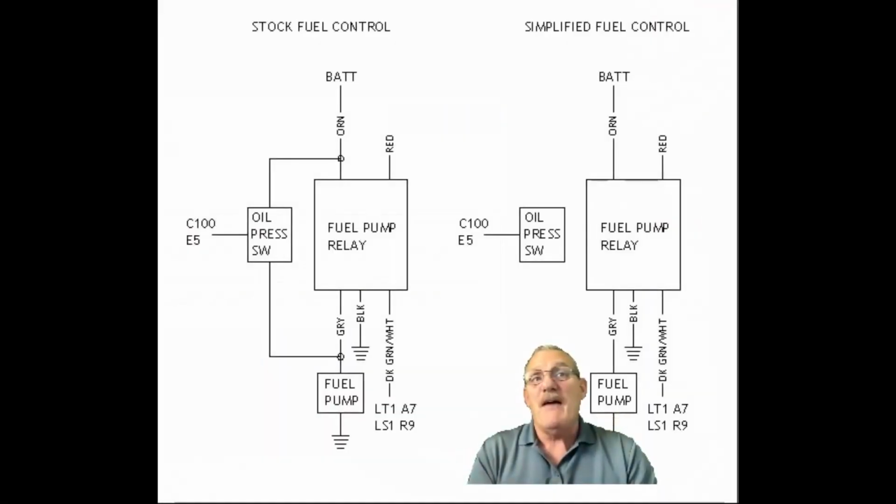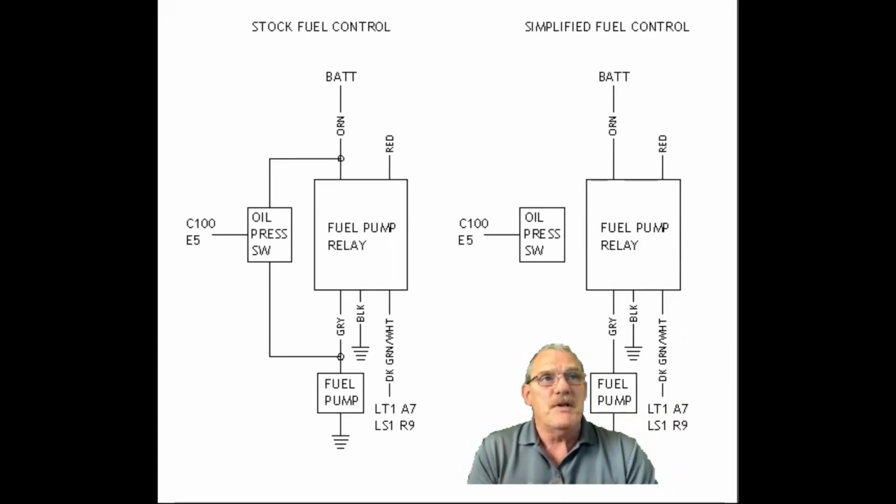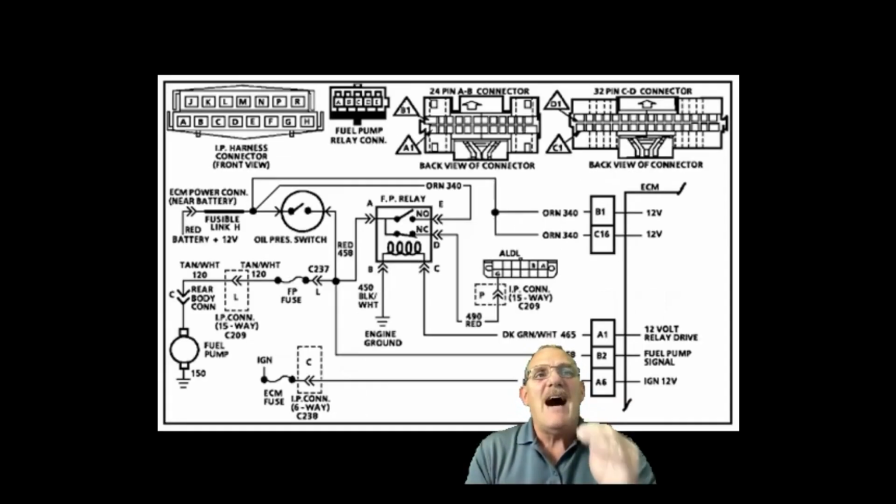This may be caused by a faulty input sensor, low oil pressure on some vehicles. Could be lots of things. The process I'm describing took less than 5 minutes to complete the test. If you had to manually test the fuel pump circuit, it would likely take you 3 times as long.